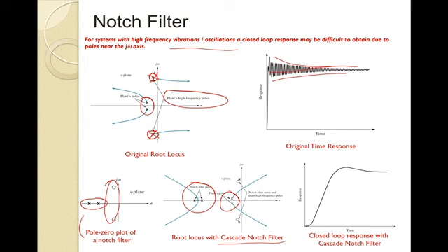But again, what you'd have to worry about relative to these plant poles is that instead of going here in a very stable, fast direction, they now go in this direction, which, depending on the amount of gain, you have to watch out for. Even though this looks good, with a little bit more gain, that could go unstable. So you'd have to watch because those poles are now migrating. They want to trend into the right half plane. So care must be taken, especially you'll have to look at this with regard to sensitivity, etc., just to make sure you're going to be good for the life of your design.